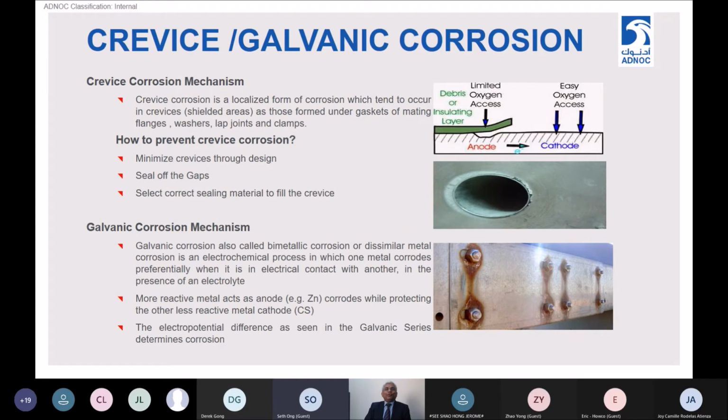Crevice corrosion damage can render a part useless, especially where you have a combination of different materials or coatings or deposition. You can have crevice corrosion occurring due to conditions either in the environment or the metallurgy or the materials aspects.